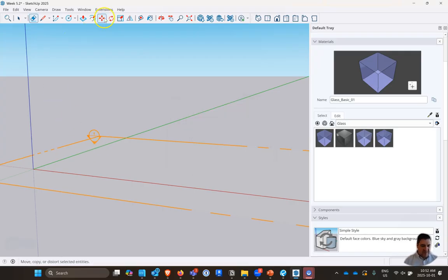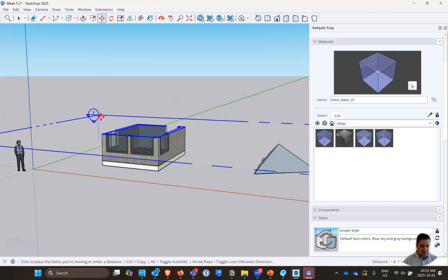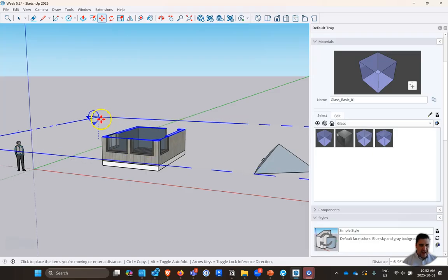And I want to move this section cut up, so let's raise it up so we're kind of halfway in. And so when it comes to floor plans, I usually try to explain this like, my chest height right here is probably around 4 feet in height. And so when we're talking about a floor plan, we're talking about 4 feet down is where we want to look. If you think about your body, wherever you think 4 feet is on your body, you just want to pretend that is the height of everything.